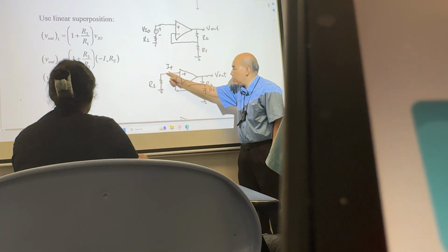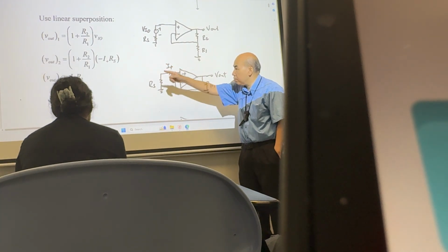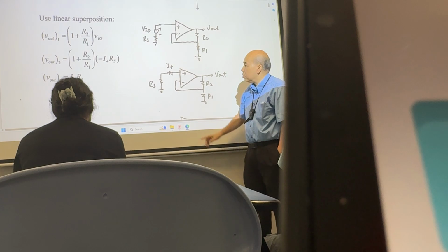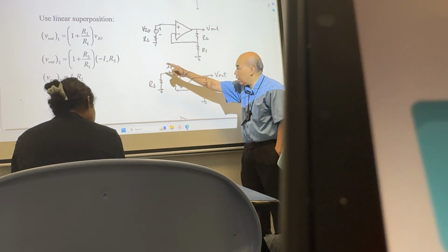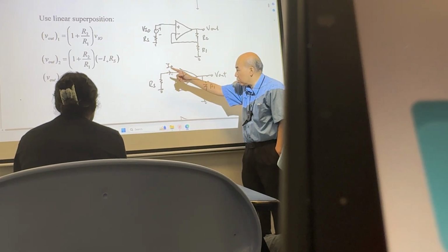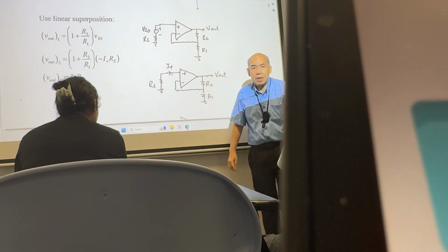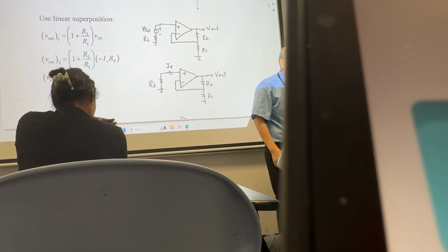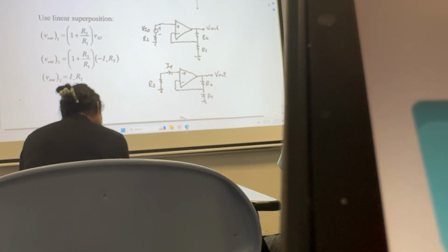When you measure the potential with reference to the ground, it is negative, negated. So the current and resistor form a voltage source, a negative voltage source, amplified by the non-inverting gain factor. Right? Very straightforward. Like the last example, you see tutorial 1, question number 6, the last part, offset comes from I minus.